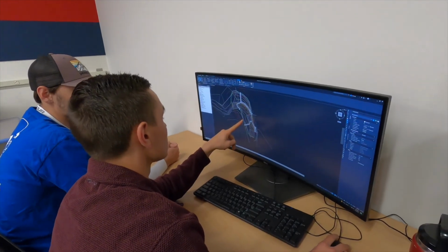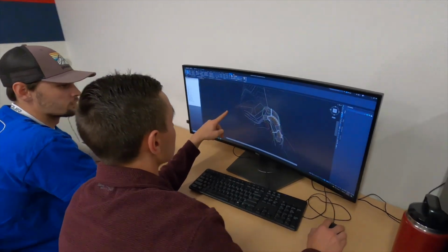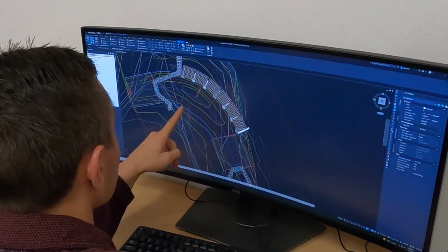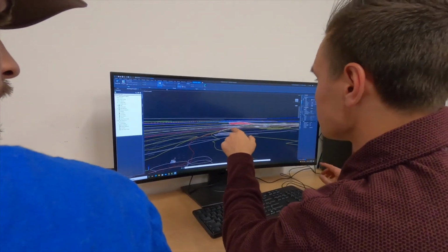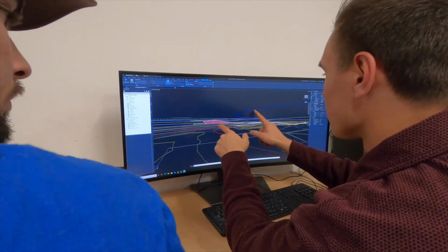Once you create that proposed design and surface, we can put stream stabilization structures in, and for our case study site, we chose a rock cross vein and a lunker layer. After importing those stream stabilization structures, you can then grade the site to determine the amount of cut and fill that you will need to gently slope the surface of the stream when you're out on site.